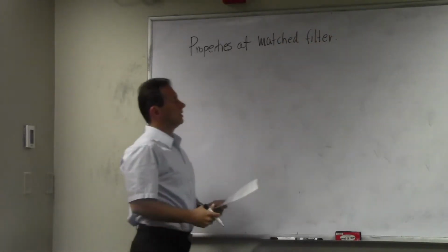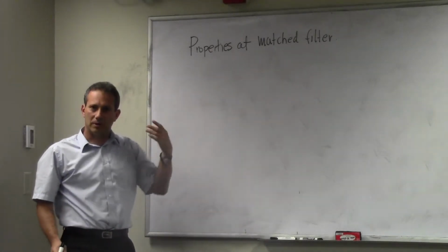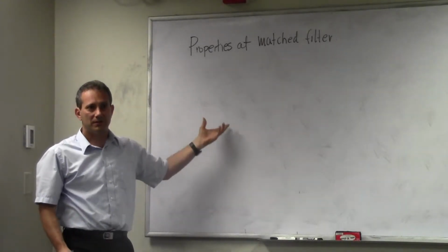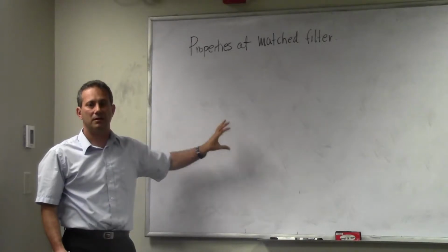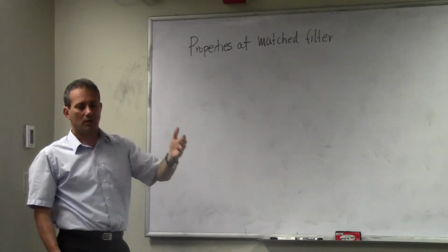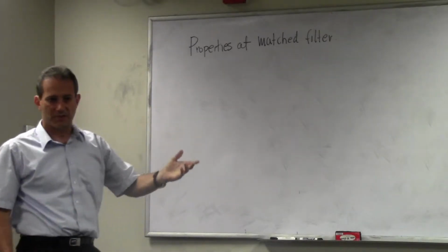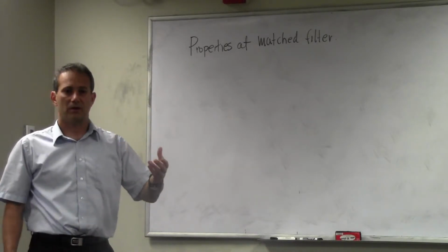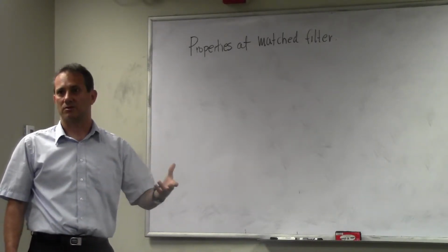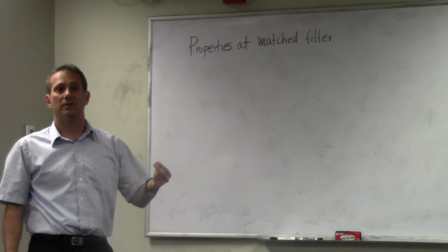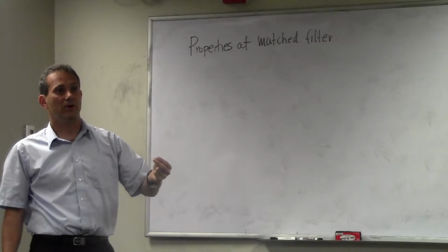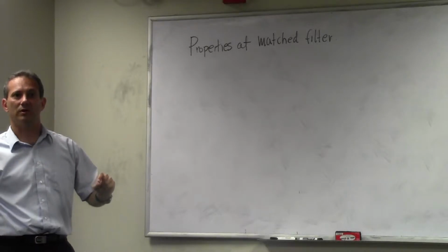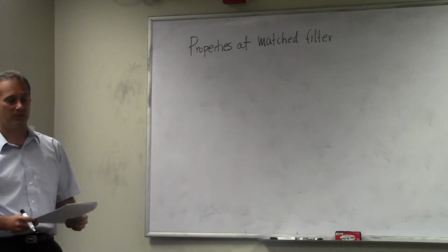And then just so that we remember that we talked about two kinds of receivers. One was correlating receiver and matched filter. The difference is really more academic than practical. In most practical applications, especially where you do all of your demodulation in DSP, matched filter and correlating receiver end up implementing the same math. So they're essentially the same thing. Both of them are taking the dot product of your incoming waveform with the basis vectors. Right? And what we need to show today is that's the best way of doing it. That's the best way of recognizing what has been sent.